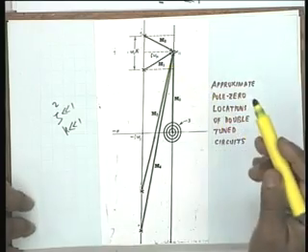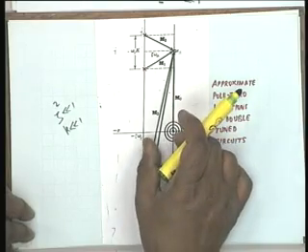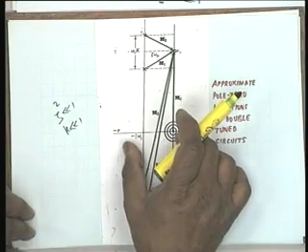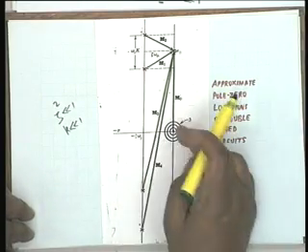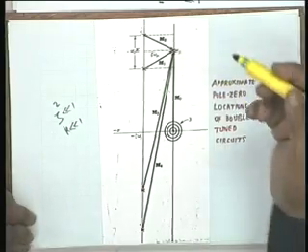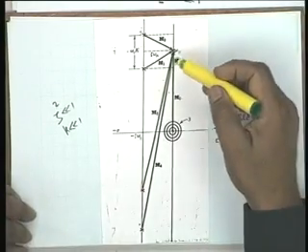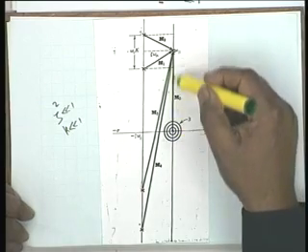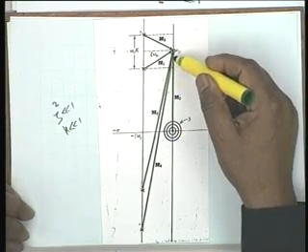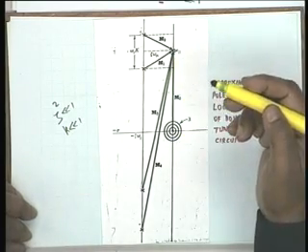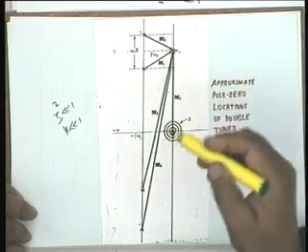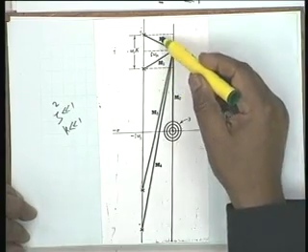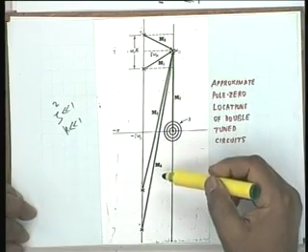This slide shows the two poles in a slightly enlarged form. Zeta omega n has also been enlarged. Actually, it is very close to the j omega axis. It is enlarged to show you the vectors which determine the magnitude. One is m0, because there are 3 zeros, m0 has to be cubed in the numerator. Then in the denominator we shall have m1, m2, m3, m4.